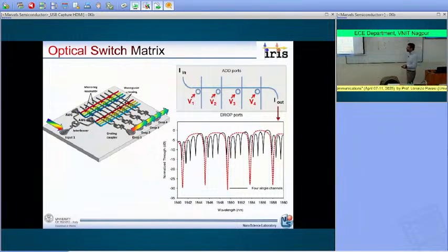And so what you see here is that the actual spectral position of this microring resonator is slightly different from the actual spectral position of this other microring resonator, that is slightly different from the third microring resonator spectral position, even though nominally they are all equal. From the design point of view, they all have the very same radius, 10 micron.